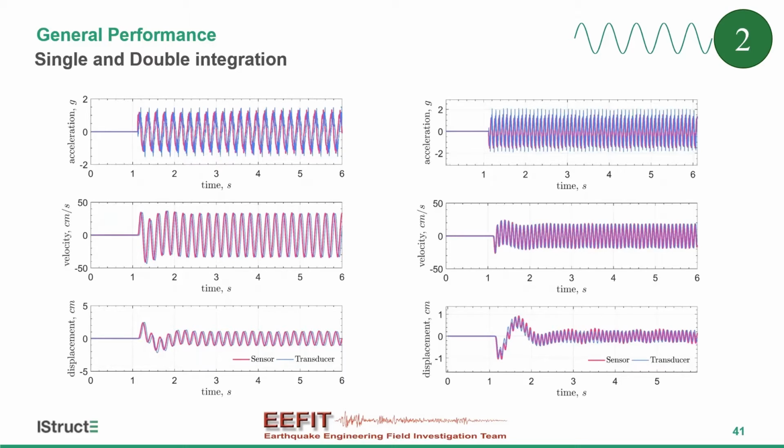Then, for a couple of sinusoidal inputs, this is very relevant for us as structural engineers, because in general we are interested in being able to recover the displacement just knowing the acceleration time series. You can perform the integration of the acceleration two times, and you can retrieve the displacement. You can see that we successfully recovered the displacement, and there is some wobbling behavior in this region, which was just the jack, before reaching a steady state, sort of ratcheting, and it was interesting that the sensor is capable of recording it.